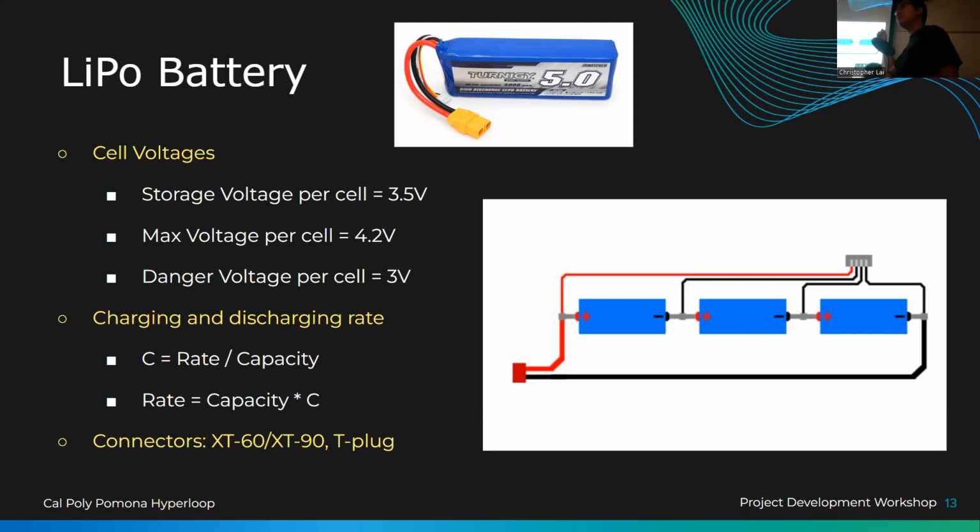Because too full of a voltage, and it will start expanding and bloating, kind of like how if you eat a lot after dinner and go directly to sleep, you will feel bloated when you wake up. Or if you store the battery at a lower voltage below 3 volts, it will start dying off. Basically, the battery will not be able to hold enough charge the next time you want to use it.